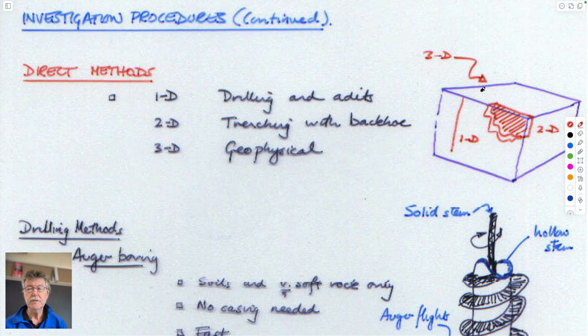So this wasn't the one I was thinking of, but this says exactly what I wanted to say. So boreholes are essentially a 1D sample, usually vertical, but not always. Sometimes they're inclined, which gives you information of what's present here. You'd like to know what the stratigraphy is, typically, and so they will let you know exactly where these interfaces are, either by changes in drilling rates as you go across this boundary, or by the samples that you take out of this, either by taking core or by collecting the cuttings that get forced up on the drill.